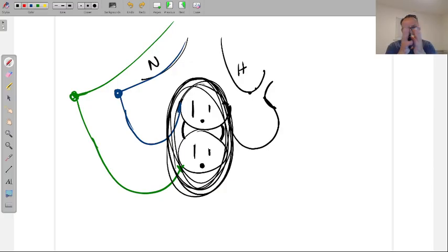And you'll see a bunch of little strands inside. So it's sometimes a little bit trickier with stranded wire, but usually if you're doing receptacles, it's Romex. So then put them together and cap it off with the wire nut, and you should be good. And now everything is safe. So now you can hold the outlet. You're a little bit more comfortable. You don't have to worry so much.